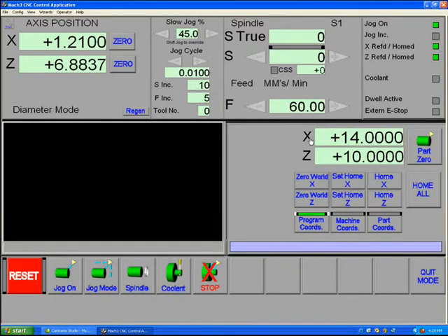Now, the Z location depends a lot on the G-code program that you've generated. Some G-codes would be posted as beginning from Z0. Others would be generated as beginning from a particular spot on the Z axis. This is something you will normally know, dependent on the G-code program that you're using. We're going to assume, for the sake of argument, that we're going to be starting at a Z of 0. This means that the tip of your tool, where it's resting right now, is a Z of 0.